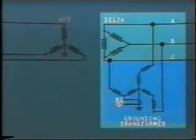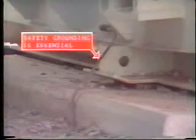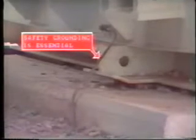Delta systems can be grounded with grounding transformers. Safety grounding is essential. All equipment in power stations, substations, switch yards, and so on must be solidly connected to the ground mat.